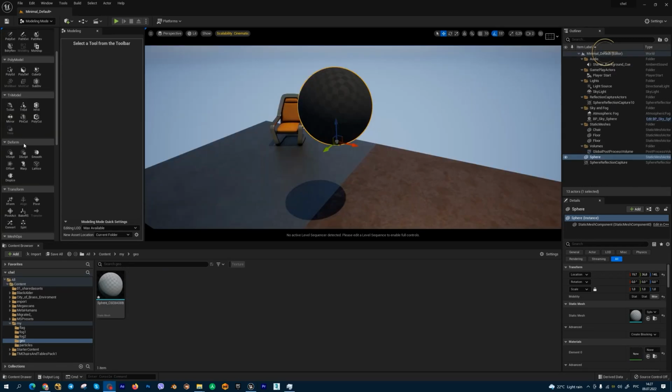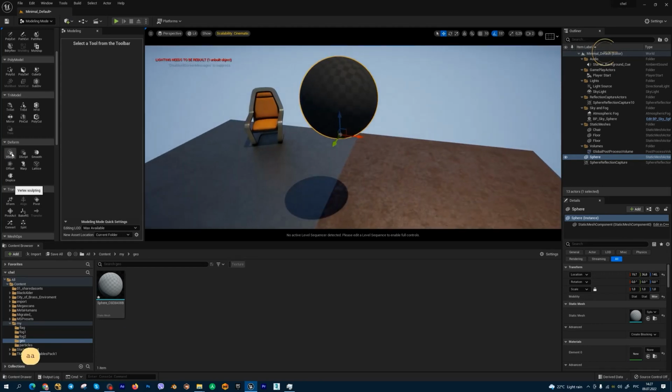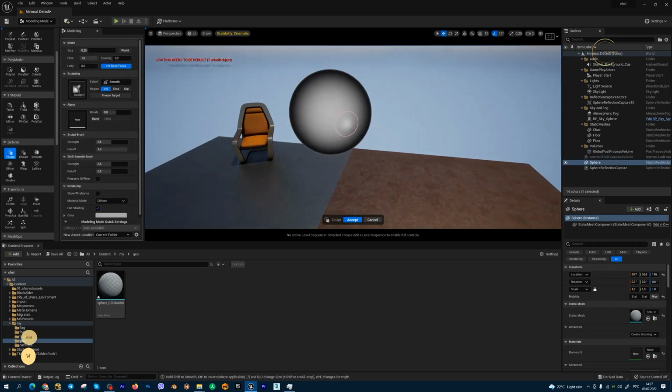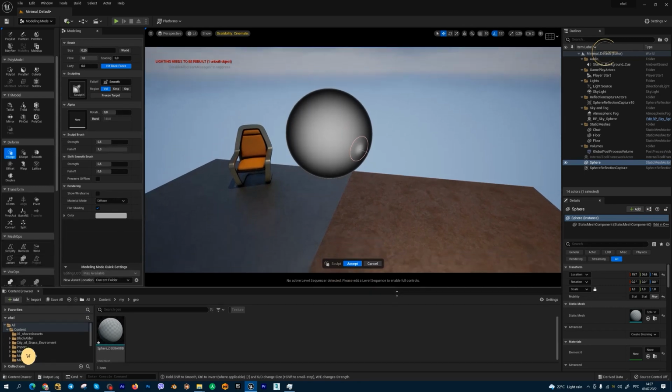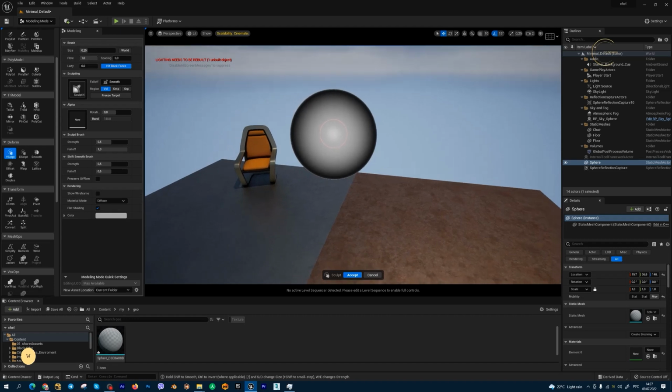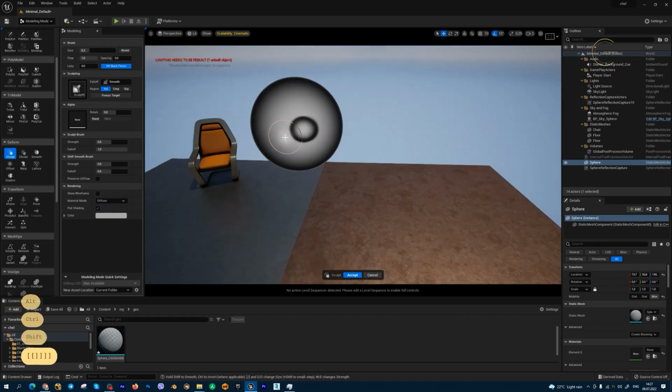Let's talk about the form tab, and first very powerful instrument is vertex sculpting. Just select your object and press V sculpt, this one button. And this button allows you create simple sculpting on your geometry. You can set up your brush size. For example, you can use left and right. We need to always English keyboard should be enabled. We can use left and right brackets to increase or decrease brush size, or you can use this parameter.